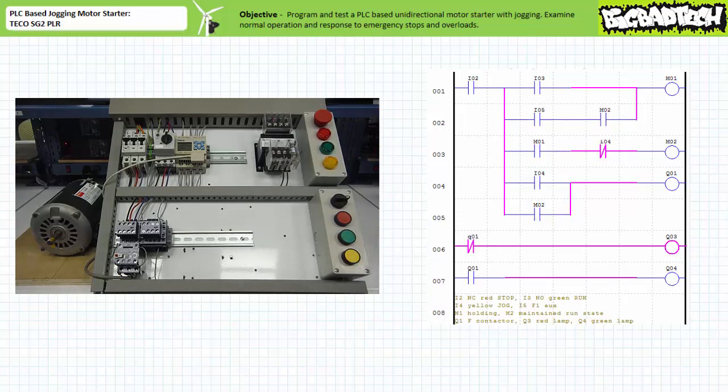The F contactor coil is de-energized, the F primary contacts open, and the motor turns off. When the E-stop is reset, the system returns to the deactivated start state and does not immediately resume operation. The system seems to correctly respond to an emergency stop condition.